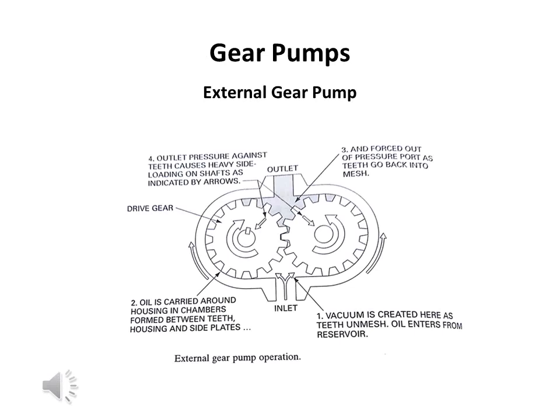In the external gear pump, there are two spur gears attached with each other inside the housing, called the pump housing. These gears move opposite to each other, and one gear is the driving gear, the other is the driven gear. The left side one is driving and the right side one is driven, and they are always matching with each other. At any point of time, one tooth will be meshing with another tooth, and the bottom side is the inlet port, and the top one is the outlet port.